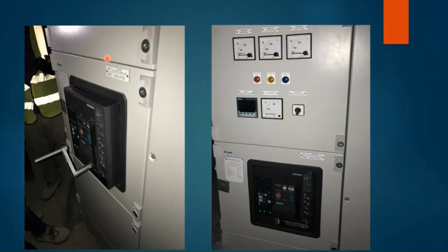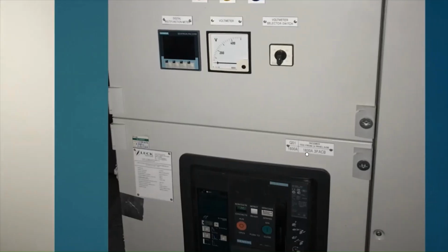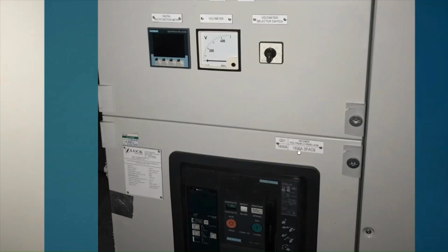Now looking at side photos of an installed air circuit breaker in a main distribution panel, we observe that it occupies larger space compared with MCB and MCCB. Also, this is a withdrawable type that can be taken out easily for maintenance purposes. This air circuit breaker current rating is 1600 amperes, which is protecting an entire project. Actually, this ACB is directly installed at the upstream end of the circuit just after the secondary side of a transformer.